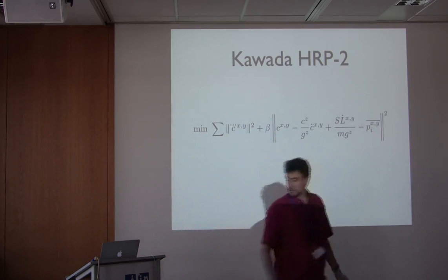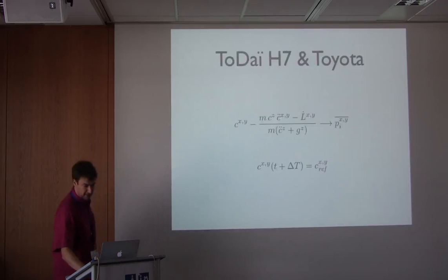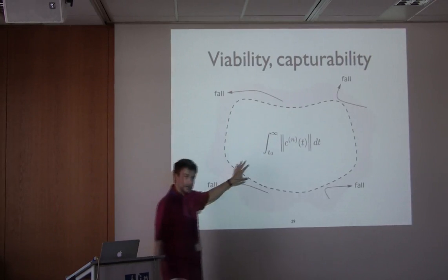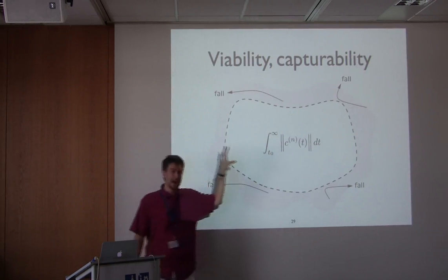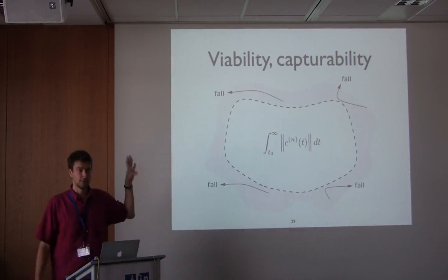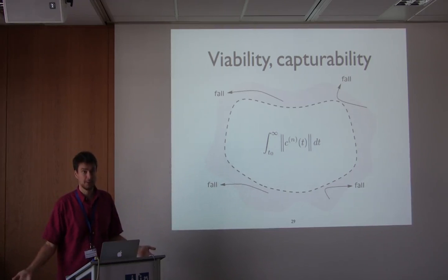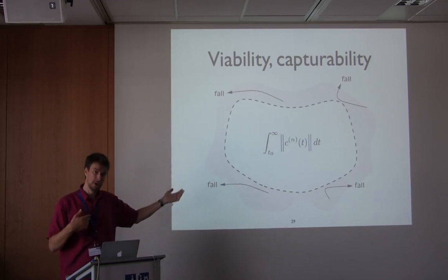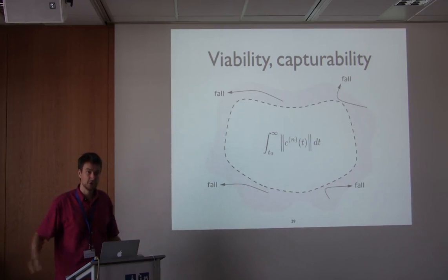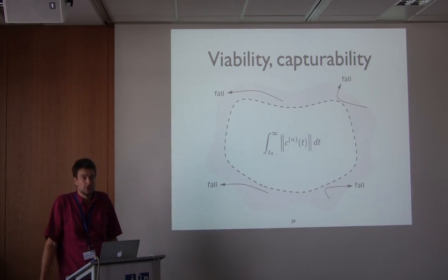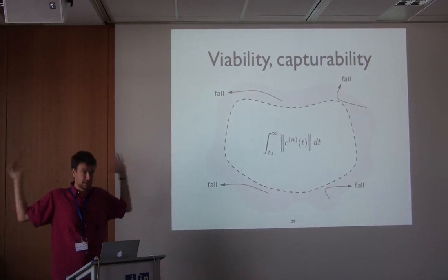What I showed here, maybe very quickly, is that if you keep any derivative of the motion of the center of mass finite, then you are stable. Because if you are going to fall, everything diverges exponentially. So you can choose any derivative of the motion of the center of mass. Kajita happens to have chosen the third derivative.